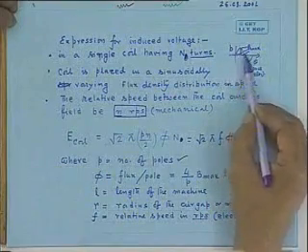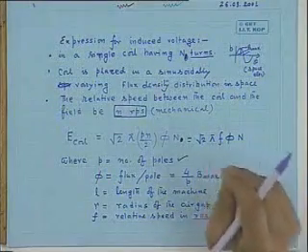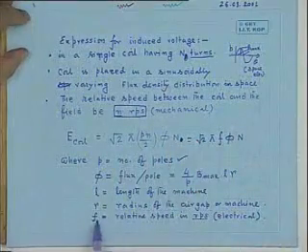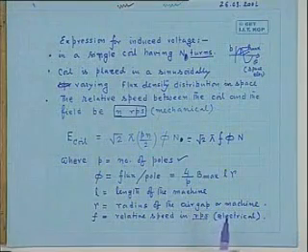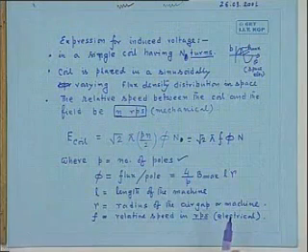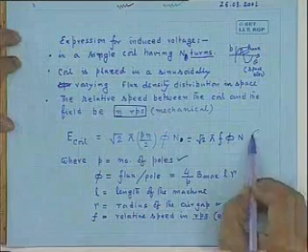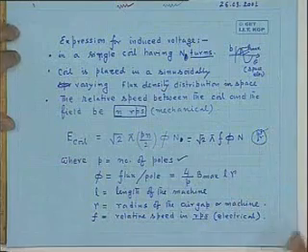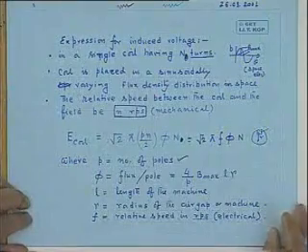If you calculate B d theta integrated over 0 to pi, remembering that d theta should be expressed in mechanical degrees because the area is mechanical. That one we did last time. R is the radius of the air gap of the machine. Since the air gap is so small, the radii of the rotor and stator conductors can be taken to be approximately equal. So wherever the conductor is placed, this is the radius. This was the voltage expression for a single coil.